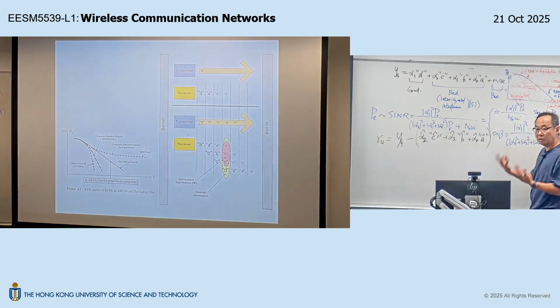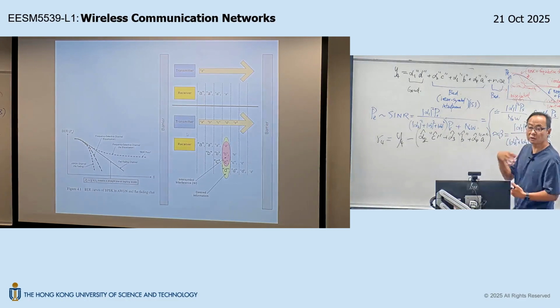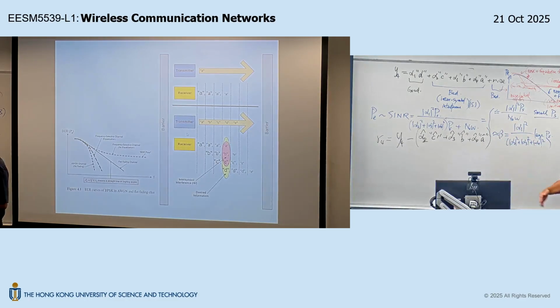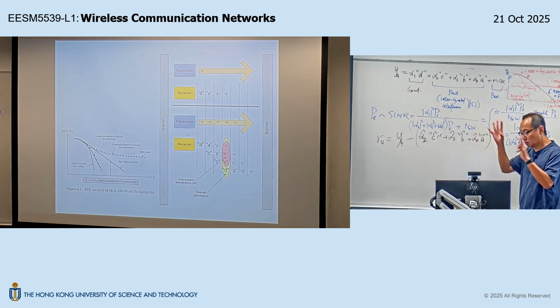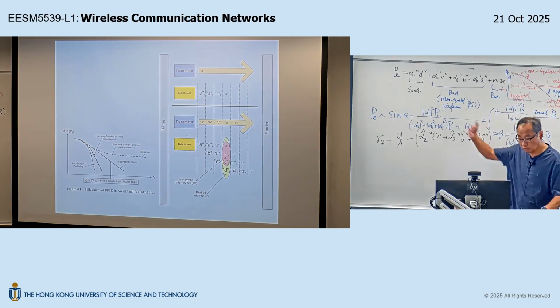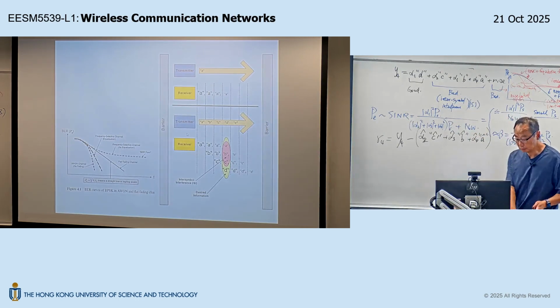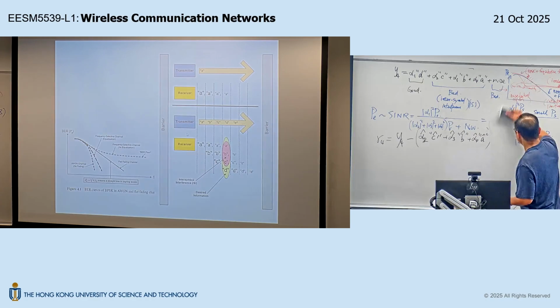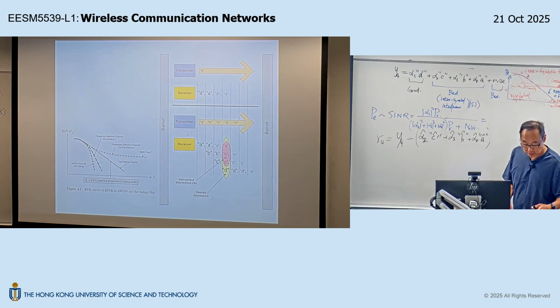Now, there are different ways to estimate the ISI and cancel the ISI. Some will do something called zero forcing projection. Some will do what we call successive interference cancellation. There are different ways to do it, so it's a whole portfolio of solutions. But in general, what I want to say is, unlike diversity, the complexity is pretty manageable. Equalization.